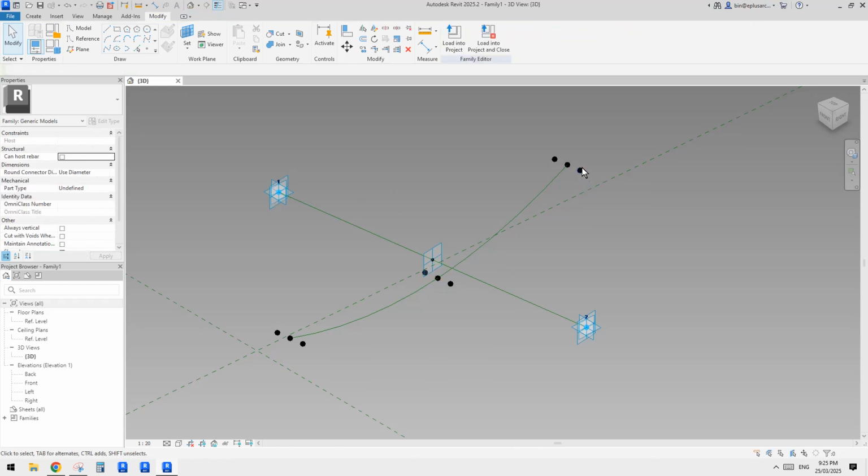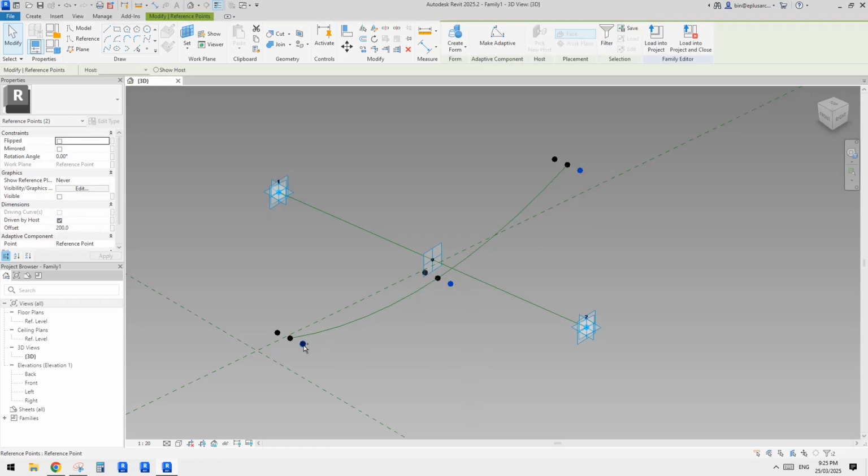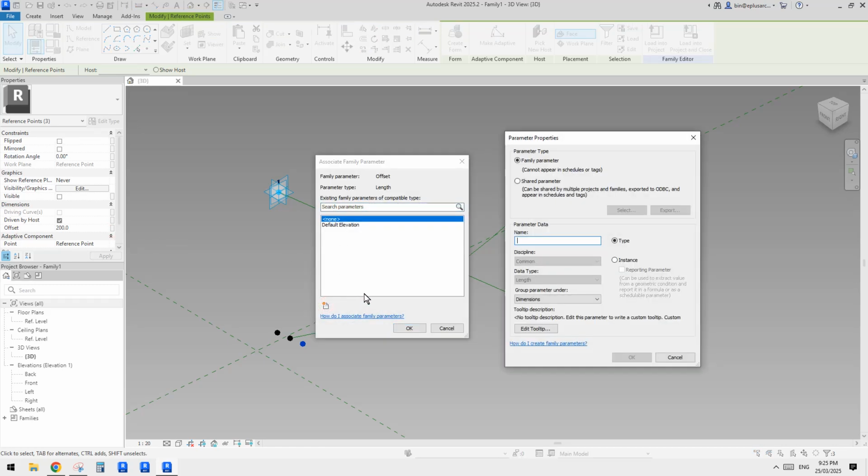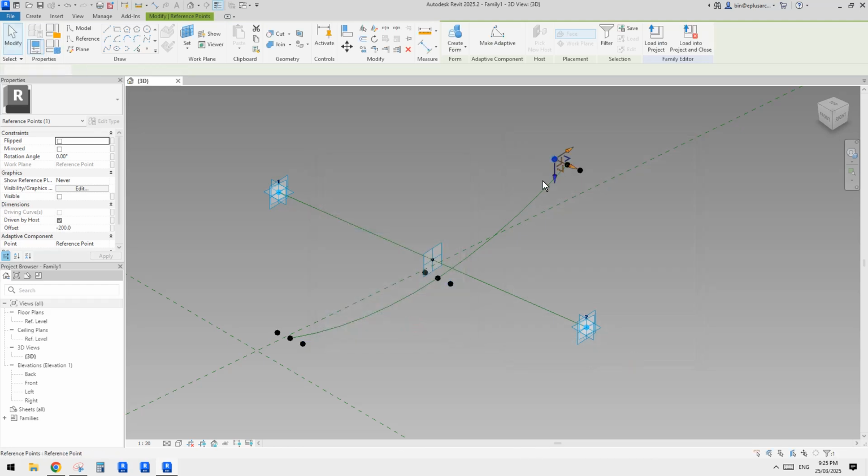So let's quickly create a parameter, in case we wanted to adjust the width of this family. Select all these three because they are all positive, currently 200. Click on this little box. We can create, we can call it, what do we call it? Half width. It's positive, so I just use half width, and maybe just instance parameter for this one. And then select the other three.